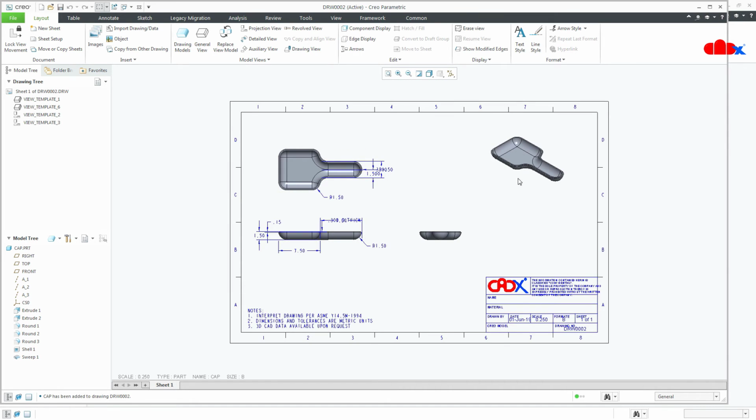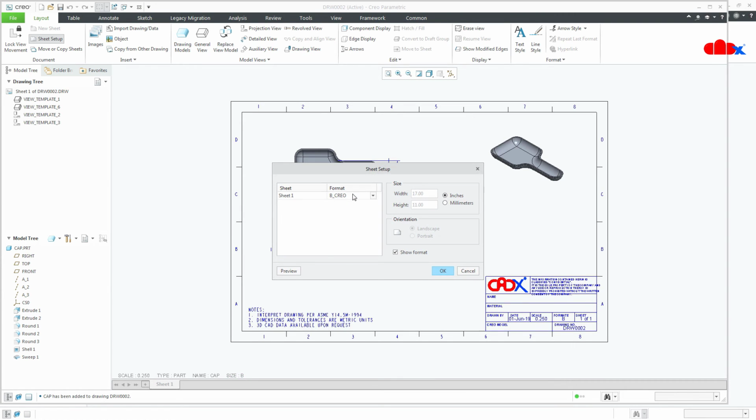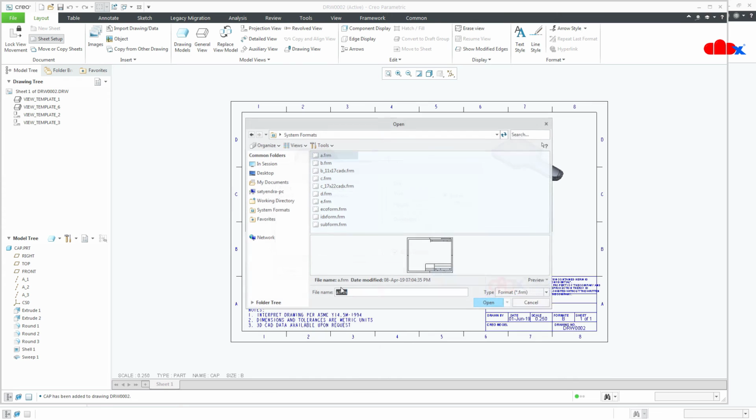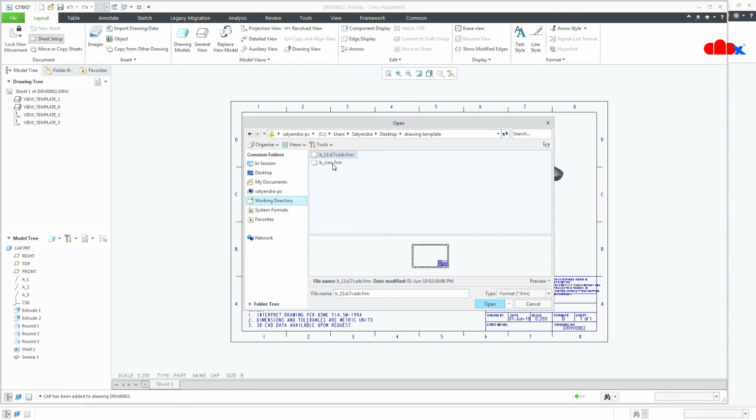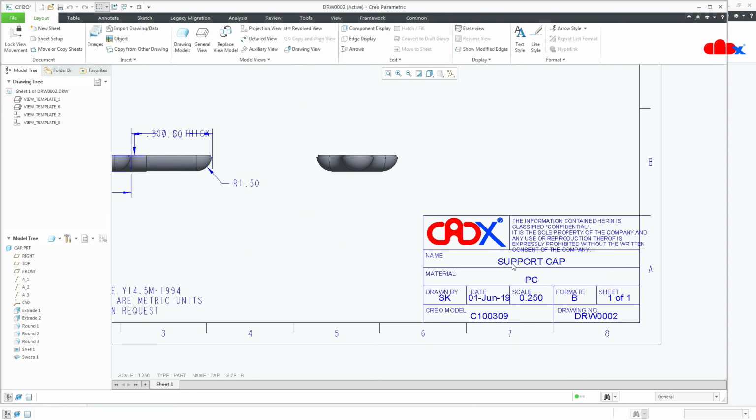Now still you can do some fine tuning for your drawing format and for your drawing template to make it better. Now you can move it, you can rearrange it once you have placed. Now sometimes when you are not getting these details in your drawing, you can reload your format once again this way. Go to browse working directory and this is the format and say OK. Remove all and say yes, and your detail is filled.